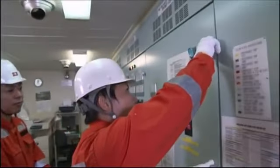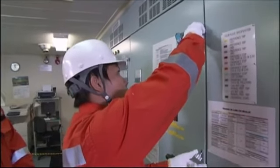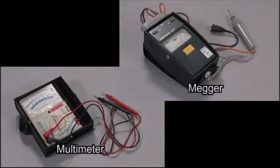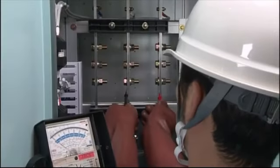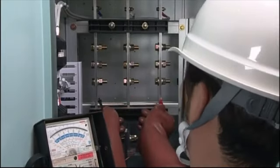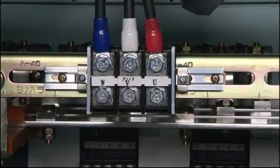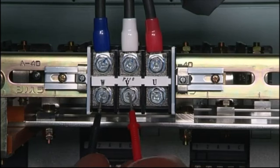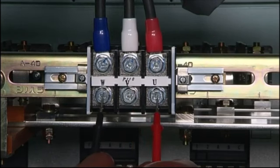When opening the switchboard door, stay away from the electrically charged section. This is the danger area. Use dedicated equipment when conducting inspections. Due to the nature of switchboard design, polarities are classified by color according to their positions. Right or left, upper or lower, or distance from the board. Make sure to confirm polarities accordingly.